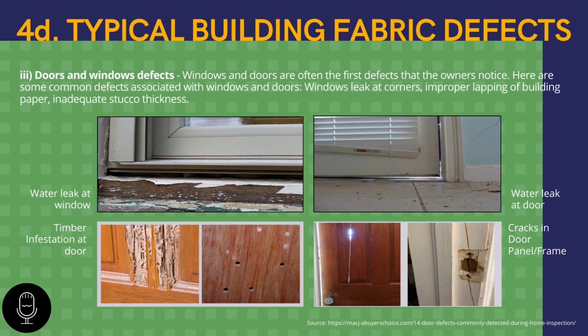These defects are mainly caused by the timber in service being subjected to environmental exposure. The most common destructive timber biological deterioration is due to dry rot, wet rot, as well as insect attack. Typically, timber decay may occur at roof timber, floor timber, and joinery timber, such as door frames and window frames.